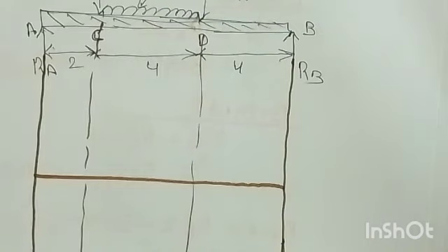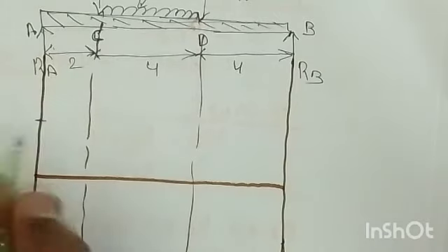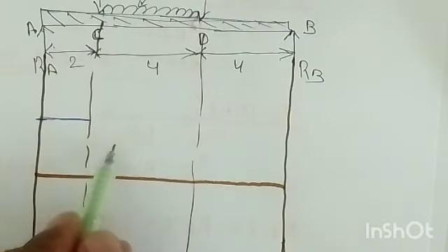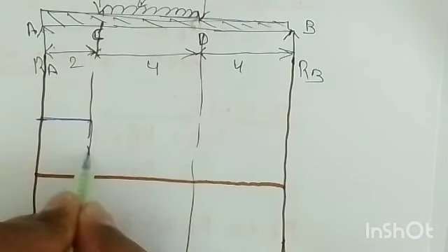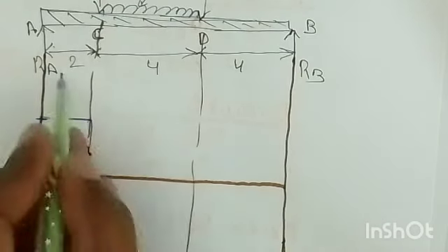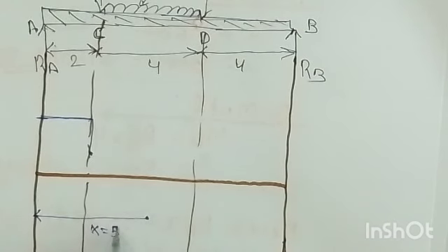Now we can say the shear force at A. So shear force at A is what? Plus 80. You can take any values, and it remains constant from A to C. Now the shear force just at C becomes 30 kilonewton, from this to this it is 30, which means you have subtracted 50. Now again, at a distance of 5 meter, the shear force becomes 0. That is, x is equal to 5 meter.